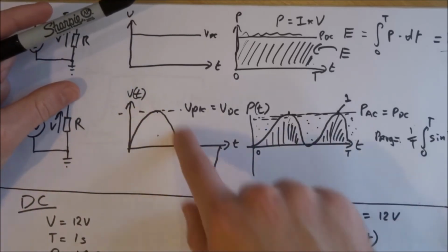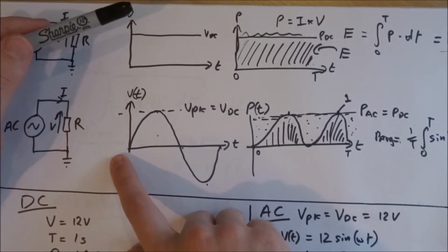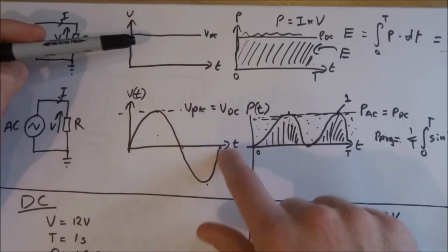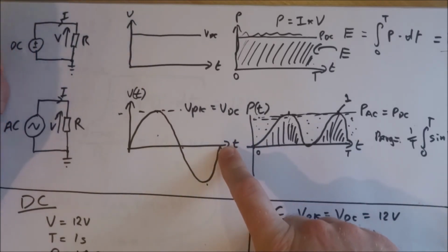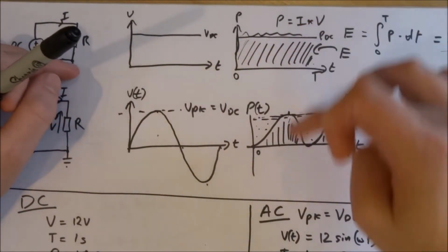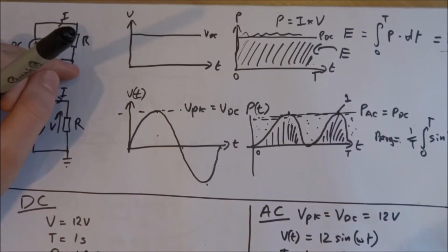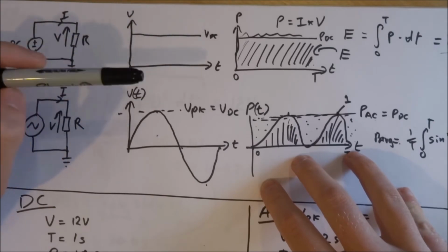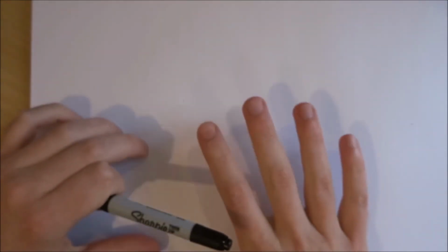But in a time-varying one like a sine wave or any other time-varying wave shape, the RMS and the average may not be the same, especially if the waveform is bipolar, meaning it has a negative cycle or half cycle. So the RMS voltages must be the same in order to dissipate the same energy in a time period. And that is the crux of the matter when we're dealing with RMS. That is why RMS is important. There is a shortcut to determine the RMS voltage or current from a sinusoidal waveform, but it only applies to a sinusoidal waveform, as I will now demonstrate.